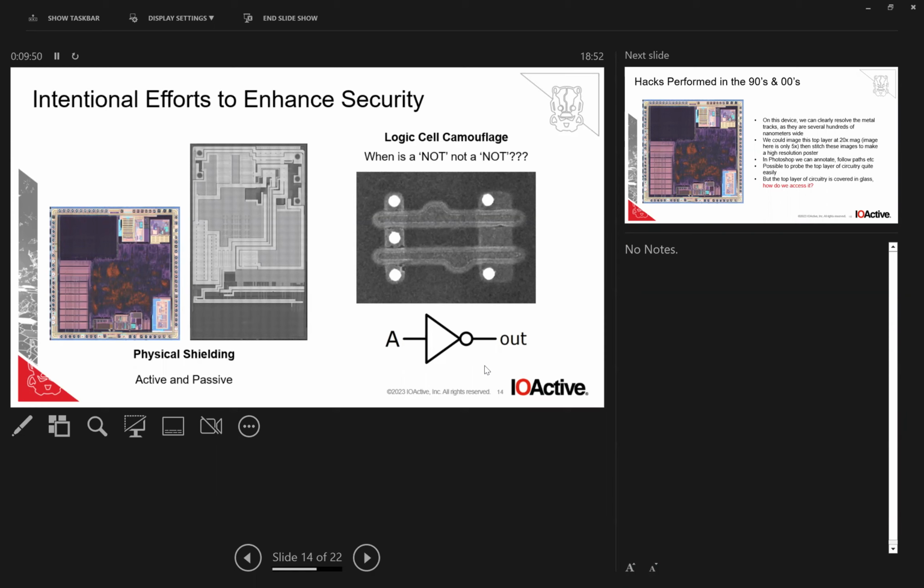The chip is covered in glass. That is what the very top layer here is. You don't see it, but the very top layer of the cross section is just silicon dioxide and silicon nitride, transparent glass-like materials. But there's one thing that will remove that material, and that's hydrofluoric acid. There's not much else that will do that. It's one of the nastiest chemicals you could imagine, but it will remove glass. Dissolving glass, it's not going to be a nice chemical.